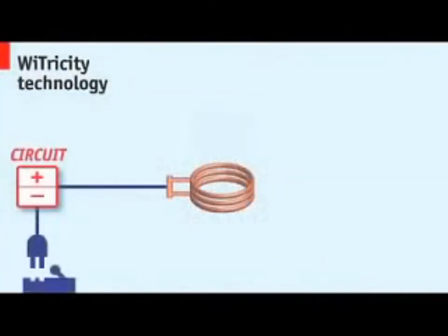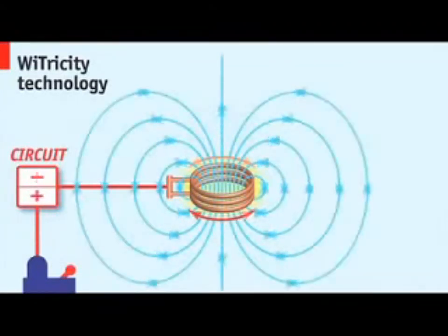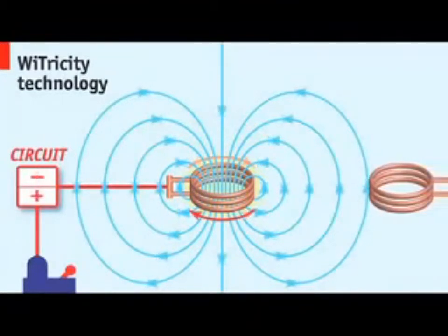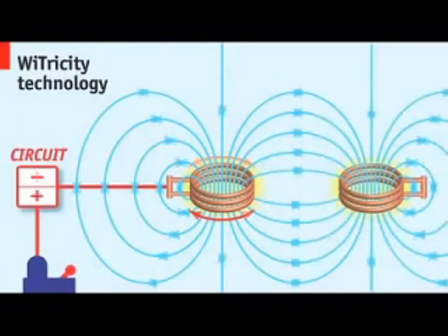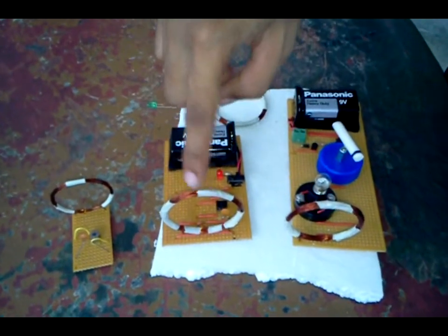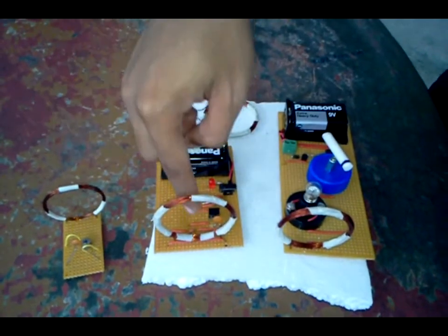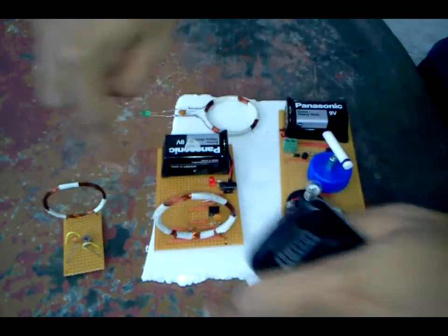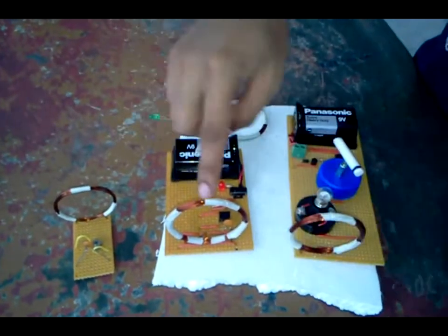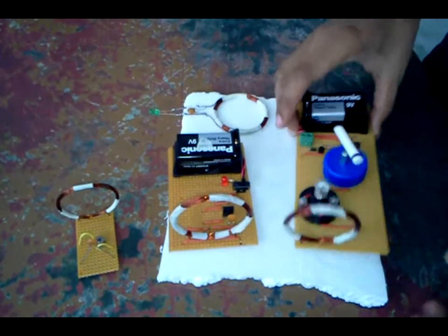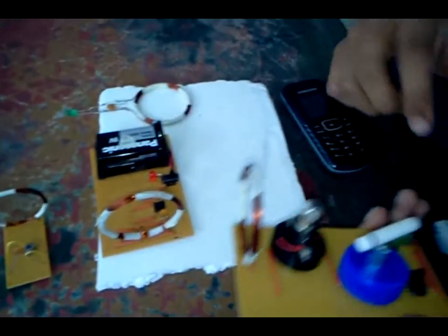The energy then builds up inside the glass until it breaks. The coils that are used to transfer power wirelessly are magnetic resonators. First, a rapidly oscillating electric current is applied to a coil at its specific resonance frequency. This will create a magnetic field in the region of the coil. The second coil, with the same resonance frequency as the source, will couple resonantly with the region and convert the oscillating magnetic field into an electrical current in the second coil. This process is called highly coupled magnetic resonance.